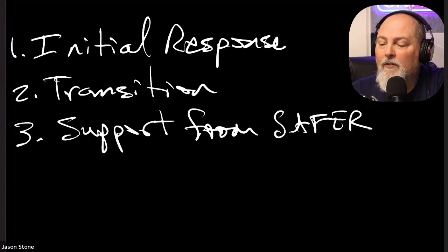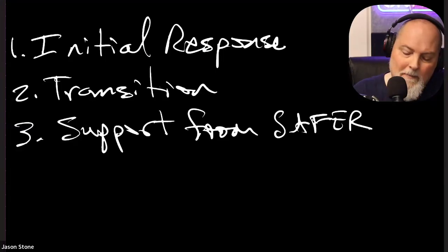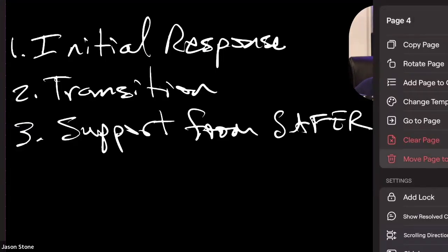All right, so that's parts 1 and 2. We've got 4 things to cover tonight. Let's talk about part 3. When I asked how the Fukushima operators knew what instruments to hook this equipment up to, well, it's because we have what we call PAM, post-accident monitoring. This post-accident monitoring means that before an event, we go through all our instrumentation and ask what will be essential to diagnose an issue during an accident.